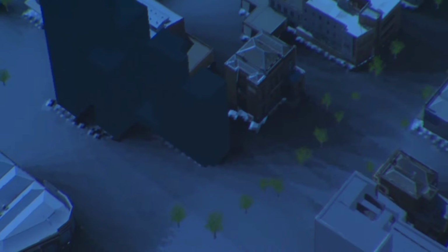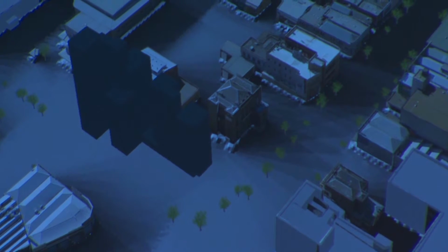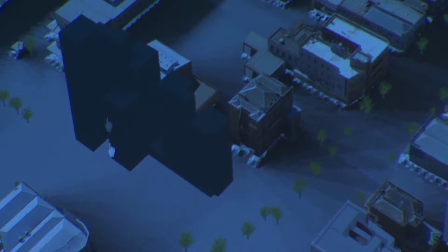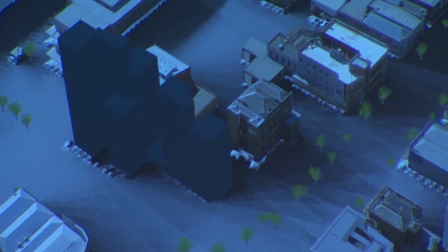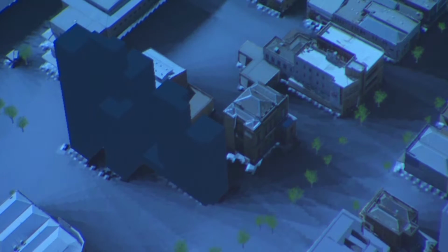And I can look at the results of that as a series of rasters on the ground. So here's what it looks like before they put in this new development. So, of course, the existing buildings that were there are much lower, so they didn't have as much of an impact on adjacent buildings. When we look at the proposed building, we can see significantly more solar impact in the area, especially on the adjacent sidewalk.